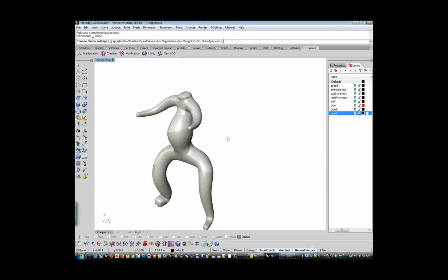My business partner Kevin Pascoe uses primitives a lot, and he just built a truck cab for us recently that was phenomenal, and it started from a cube, so it's personal preference as to what you like best. Sometimes I like to use curves if there's a very specific shape I have to hit, but most of the time with T-splines, one of the real benefits to me as a designer is that I don't have to get all that tight to start with. A lot of times I'll start laying out patches and pushing forms around until I see something I like, and then develop it from there, which is fantastic because it's difficult to do in NURBS.